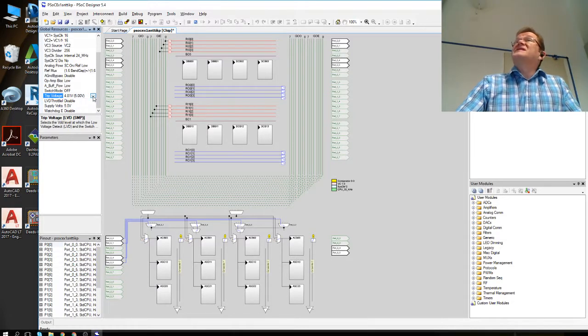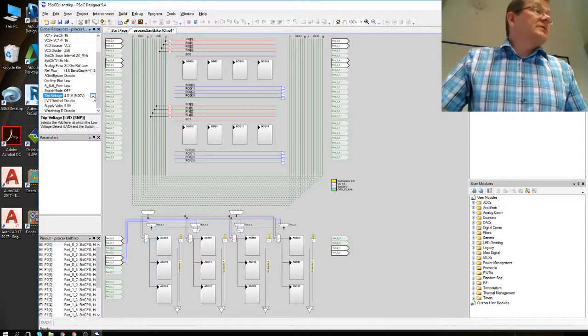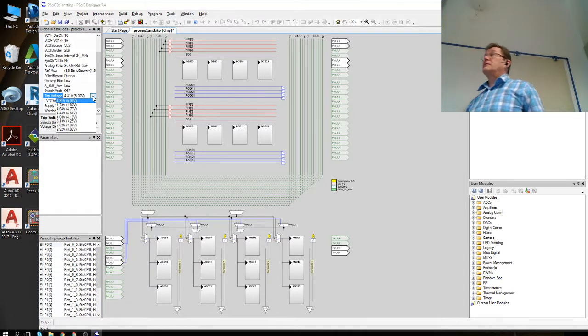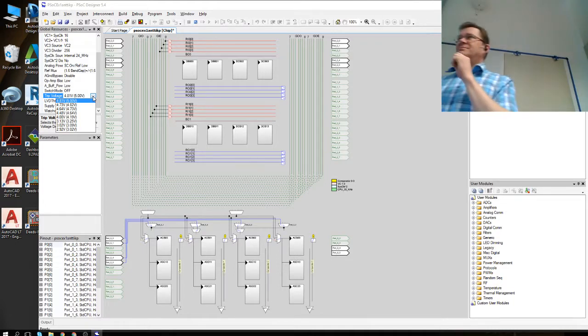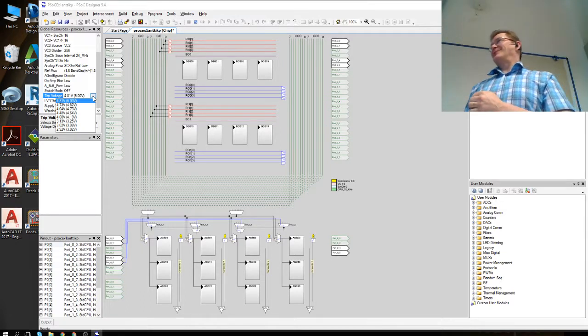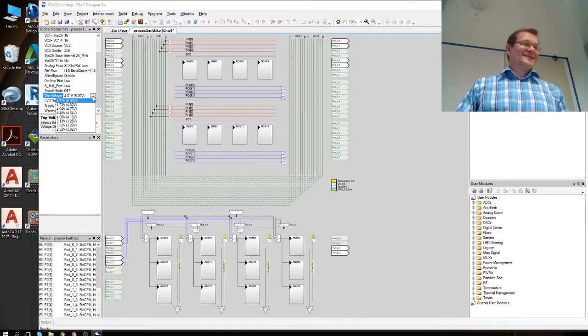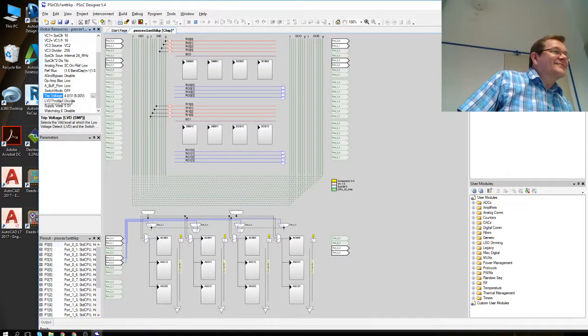This has a low voltage detection, so you can set where the low voltage detector actually turns on. So this one makes the low voltage interrupt, which causes halt almost in any case. You can actually also make your own code to prevent halting and browning out the circuit. Okay. And there's a low voltage throttle back, something like that.